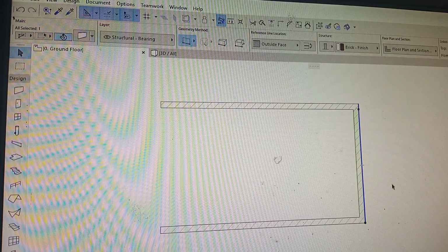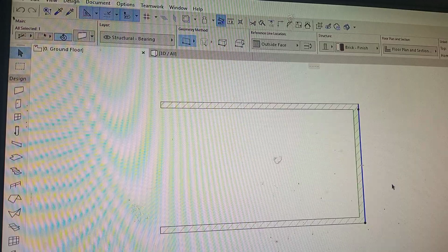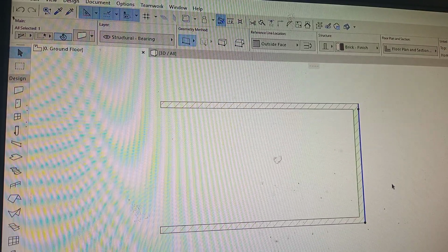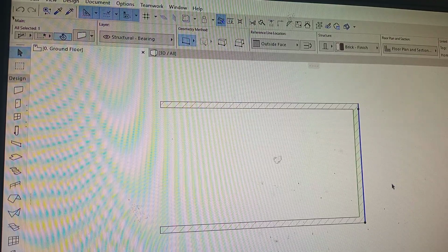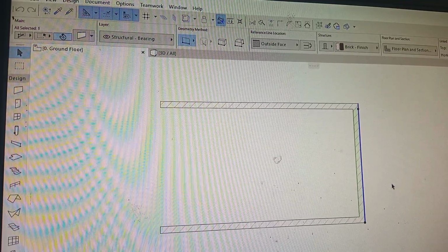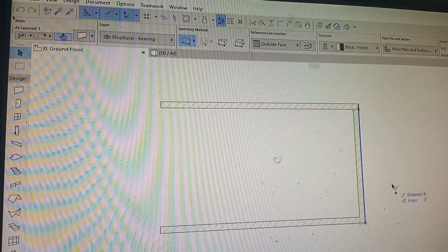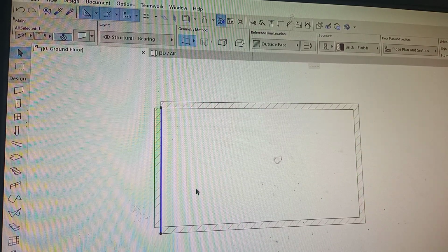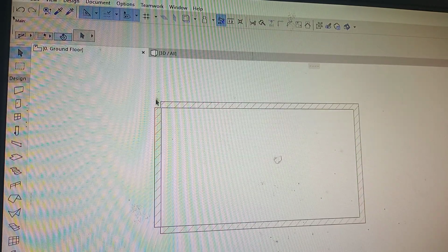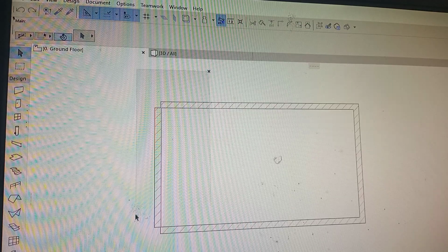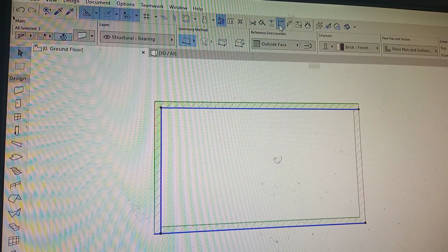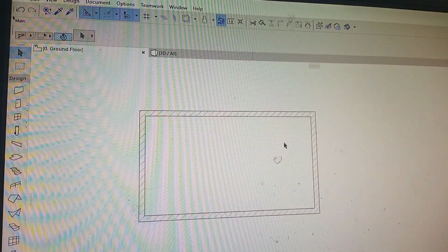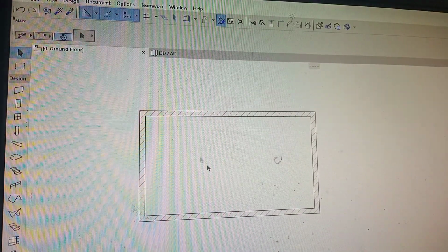So we can use this other shortcut that I showed you. Control, select the wall you need to create a shortcut. So press Control D, Control, then left click, then move, probably there. So you see this gap, we need to intersect it. So you select your wall, come back to intersect, probably it will join your wall as you want it. So basically this is our wall.